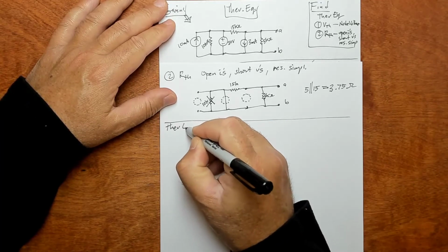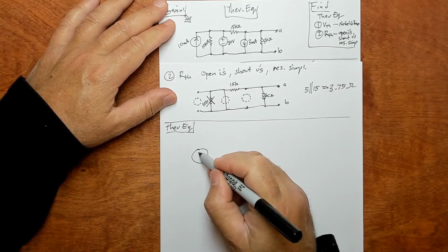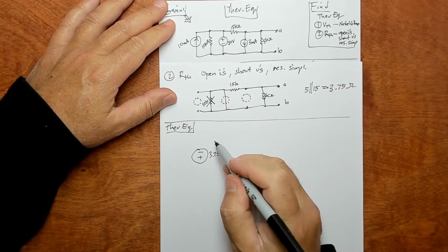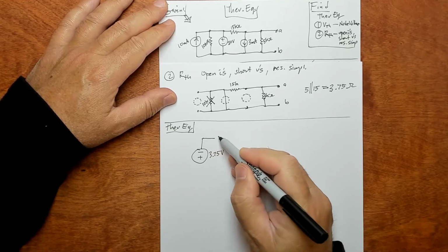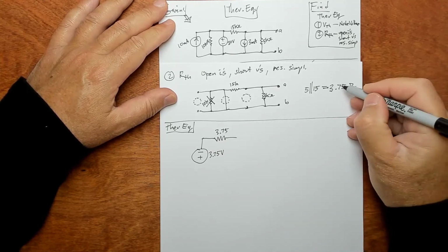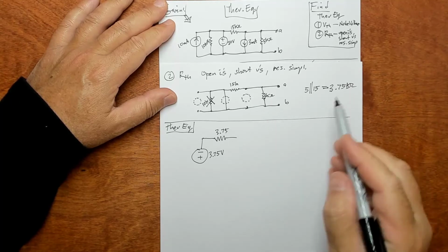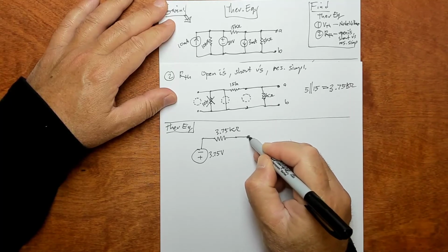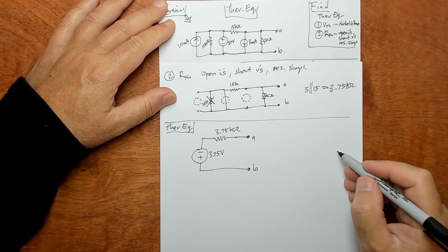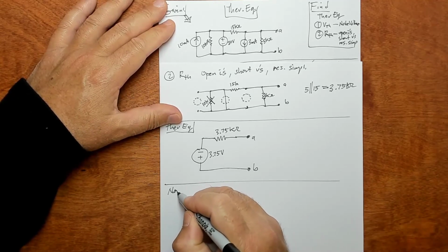So then there's the Thevenin equivalent, which is what we're trying to find, is this guy. And I'm going to go ahead and flip the sign and use the positive 3.75 volts from before, just because I don't like negative quantities of voltage and stuff. And then this guy, which is a 3.75. This turns out to be kilo ohms. Oops, kilo ohms. Because it's 15 kilo and 5 kilo. You have 3.75 kilo. That's it. All right. That's pretty much what this question is asking.